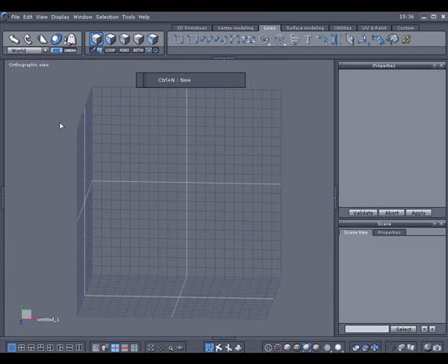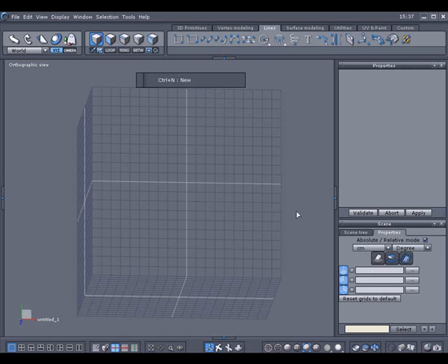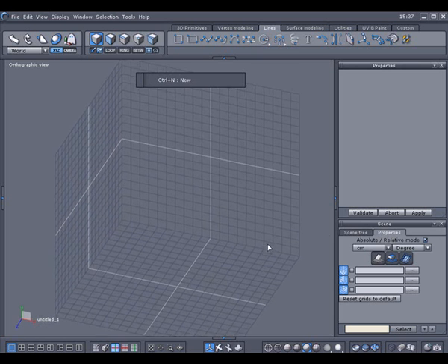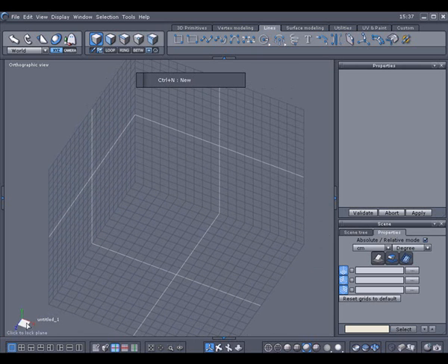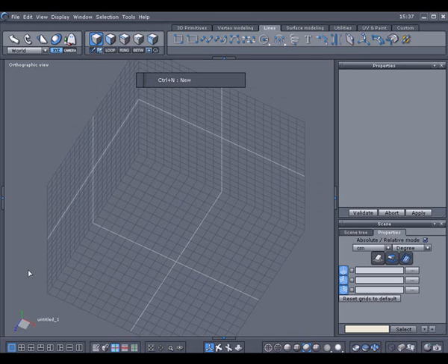Alright, I'm going over to the 3D Trihedron. It's down here in the left hand corner. It's got X, Y, and Z, different colors, and this transparency plane. Now this transparency plane basically represents one of these floor grids over here. We'll select here, and when I move around, they'll both update at the same time. As you can see, it flipped down here. Let's do that again. It's trying to tell me the best view right now would be this plane here, which actually would be the floor plane.